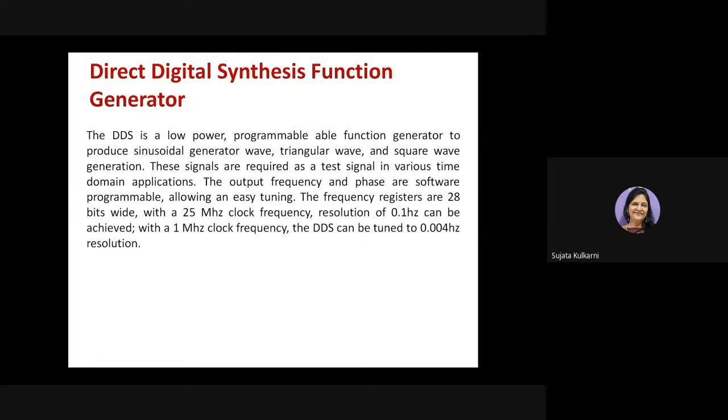But since we are implementing a completely digital system, through software we want to implement a programmable function generator. So we were looking for a direct digital synthesis function generator, DDS. DDS means it's a peripheral interfaced to a microcontroller, and you write a couple of control words, then it will start generating the waveforms as per your desired frequency. So no hardwired function generators, because we want a programmable version.